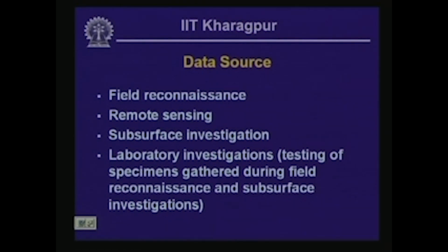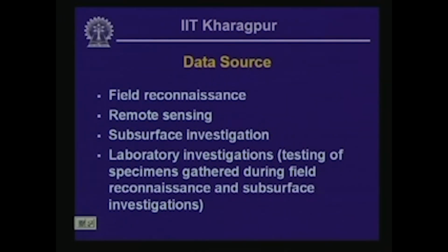Then additional information could be available from remote sensing, and subsurface investigation also may be required in some situations, as well as laboratory investigation, which includes testing of specimens that were gathered during field reconnaissance and subsurface investigation in the previous steps that we listed there. So, all these things together form the activities that require to be undertaken for the construction of a geologic map.